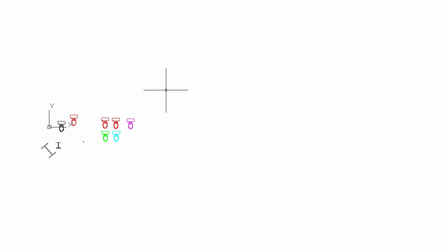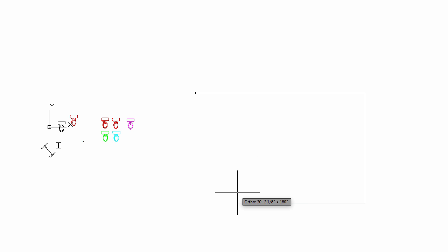And what I'll do is I'll just draw a quick little floor plan here. We'll just come in here and turn ortho on, and we'll go 40 feet. Oops, undo that. We'll go 40 with a foot mark by 26 feet. Just a typical ranch style house, okay? Something like that. Then use offset, 6.5 inches for the exterior walls. So we'll do that sort of thing.